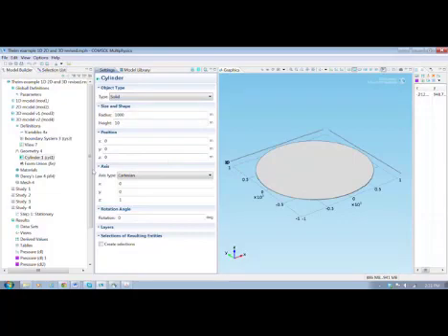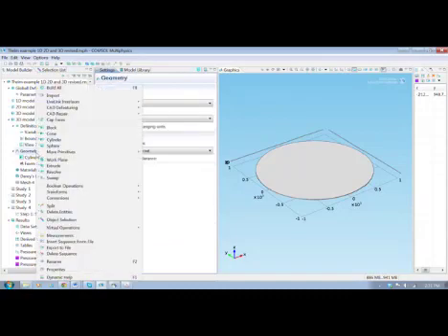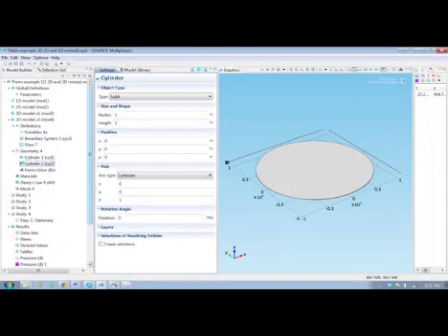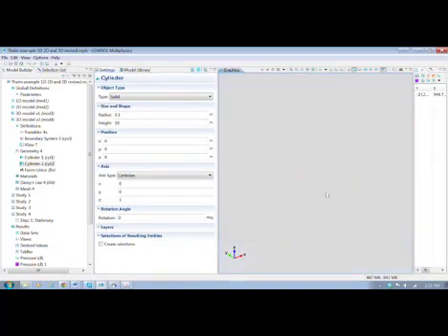So there's the aquifer. But now in the previous one we had the well be just a line element. We can do it a little bit differently. We can put in a cylinder that has a radius of 0.1 and a height of 10, and that appears right there. And now we'll say that that is the well. So let's take a look. We'll make it go transparent.